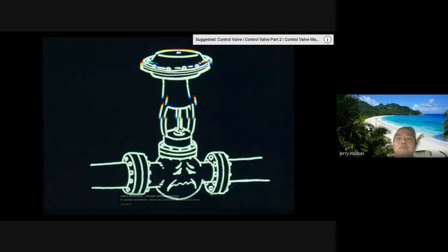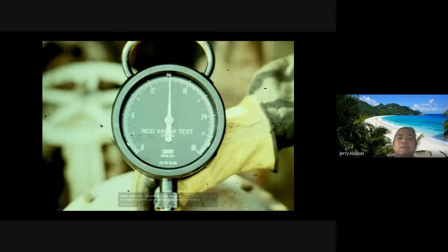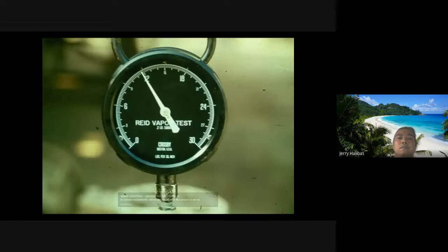If the controlling instrument output signal, the signal at the valve, and the valve position do not correspond, there is a malfunction. Ask the operator to bypass the valve. Install a 0 to 30 psi test gauge at the control valve. Verify that the controller output and valve signal agree. Let's assume the controller output is 100%, but we are receiving only 12 psi at the valve.